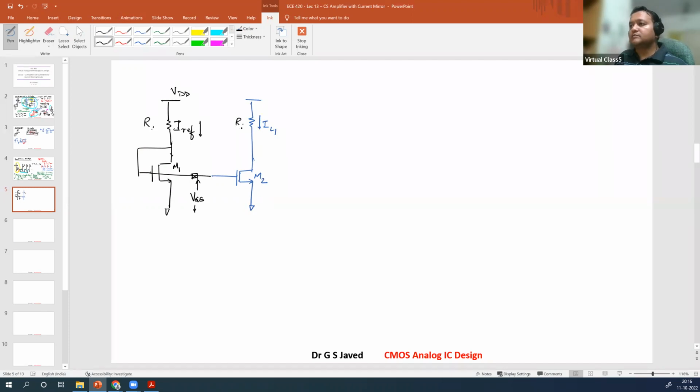This is R. This will be RL1. Now, if you want to do PMOS, what you could do is take the same tap off point, first create an NMOS, because you have to mirror this, right? So now with this stage, you are expected to get IL3, right?